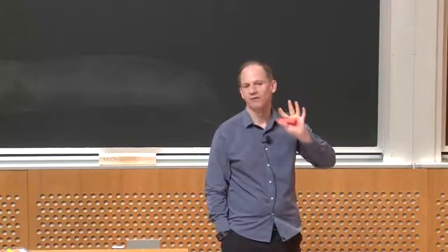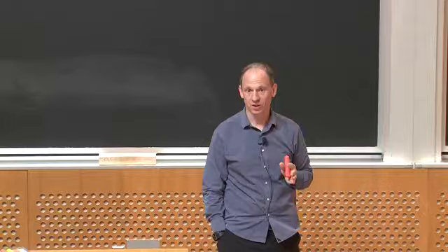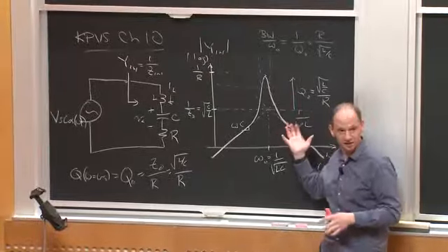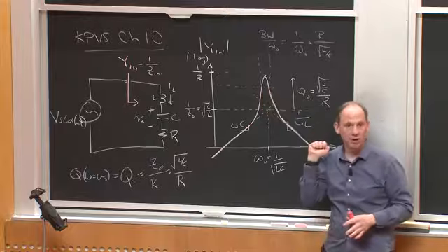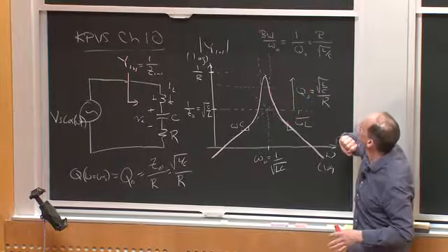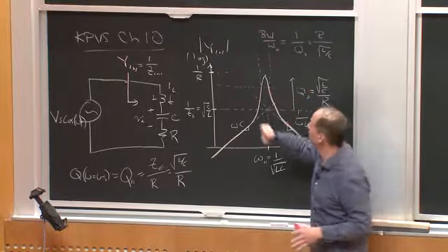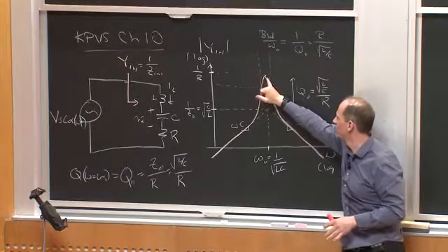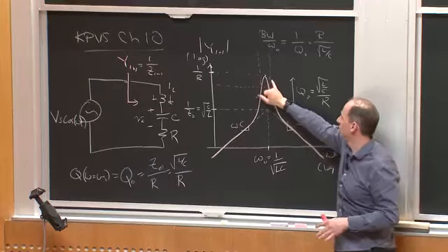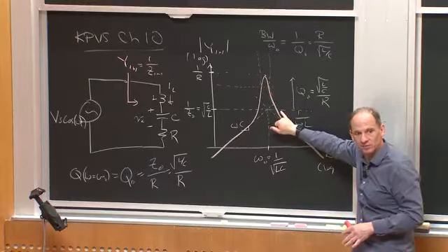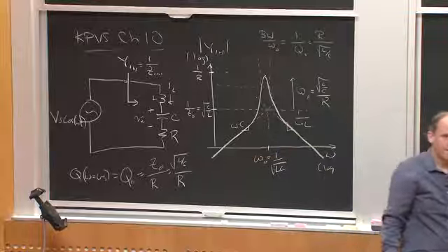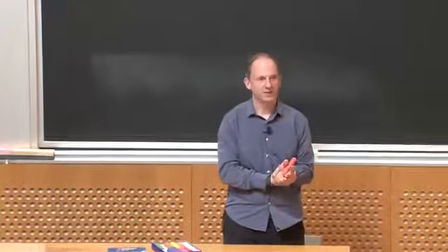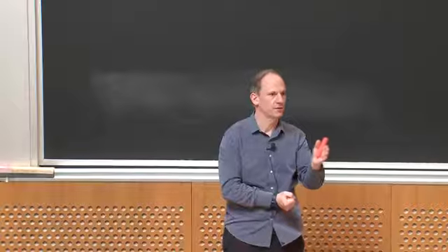But to first order, for basic analysis of resonant converters, we often make the assumption that, as far as the current I'm going to get is concerned, I can just focus on the fundamental and think of that current as being a sine wave with a magnitude that's determined by the magnitude of the voltage I'm driving with, times the amplitude here in terms of the admittance. Any questions about that? And then, of course, the power is then I squared R. So we get a lot of attenuation. We get a very steep characteristic as I vary frequency. Okay.